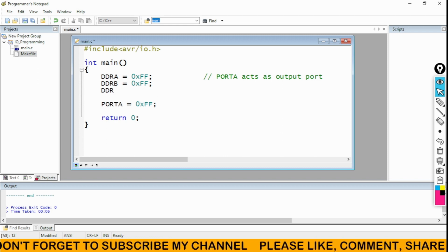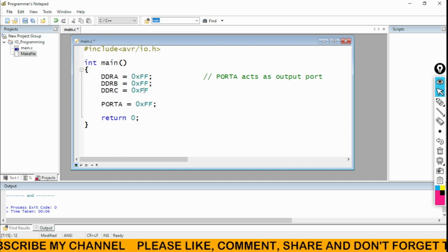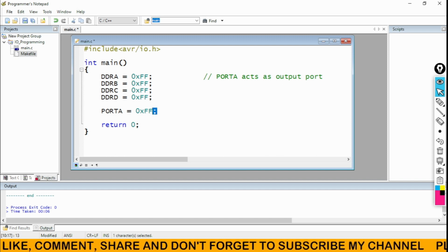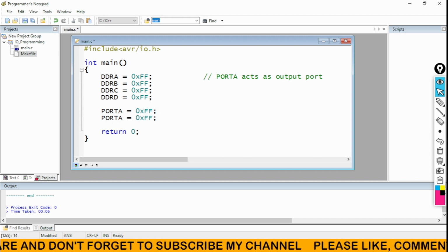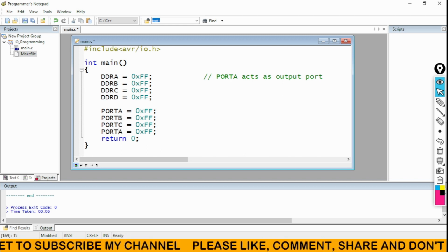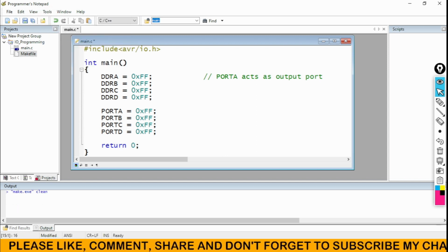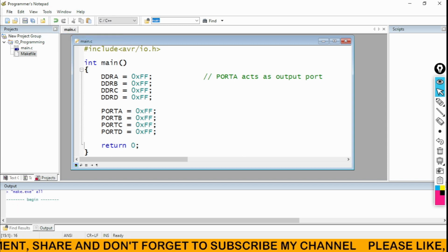Okay, I'll take DDRC 0xFF and DDRD 0xFF. Then we'll copy and paste all these things and make the changes as port B, port C, port D. We'll see that if we run this particular code, all ports should get the value 1. I'll just compile it to create its hex file.